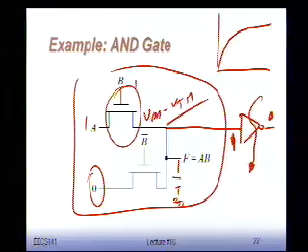Now suppose, for instance, that the NMOS and PMOS have approximately the same threshold. It means that when this is VDD minus VTH, my PMOS is going to be on the edge of conduction. We're just applying an input voltage, VGS is going to be equal to VT. That would already be bad, because there's already a substantial amount of current flowing. But it's worse, because body effect plays in. This threshold drop is going to be larger, because it's the NMOS VTH adjusted for the body effect.